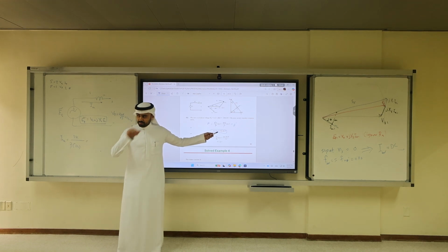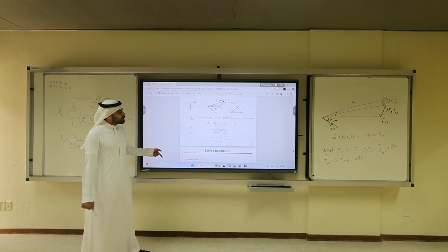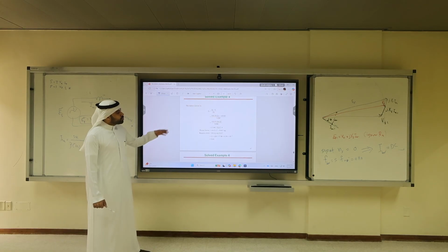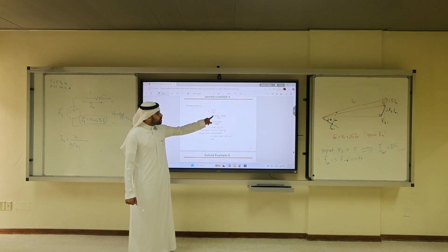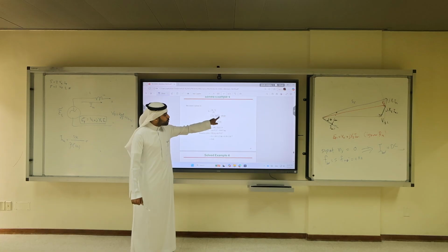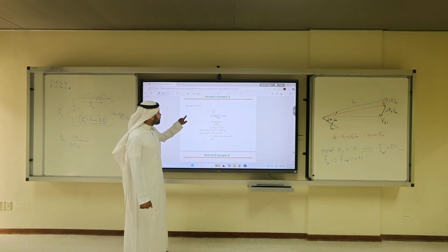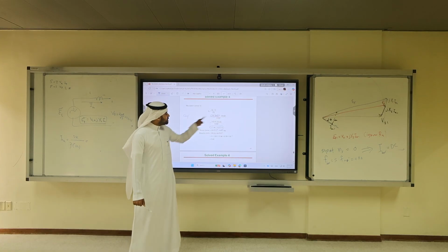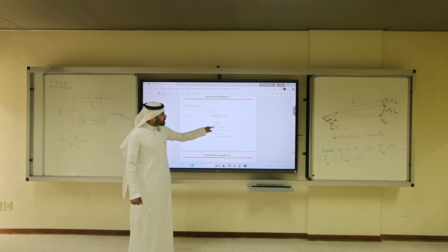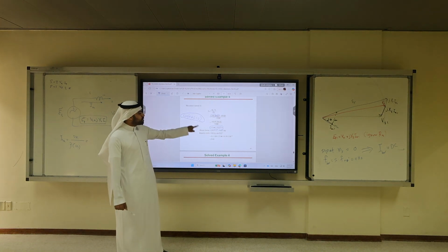This is trigonometry. We're equating the two powers. We increase the field by 20%. So now with the new EF, 1.2 times the part A value at an angle of 21, this is Vt, this is jXs, you get the new value of 17.86, and the power factor is cosine of Vt angle 0 minus 51, so it will be cosine 51.5.